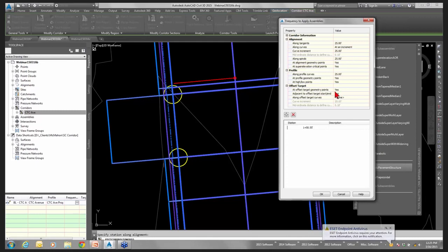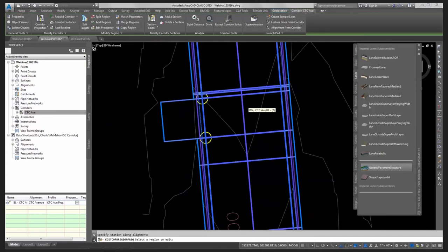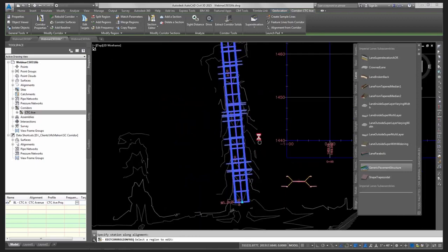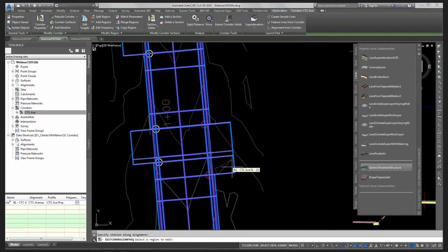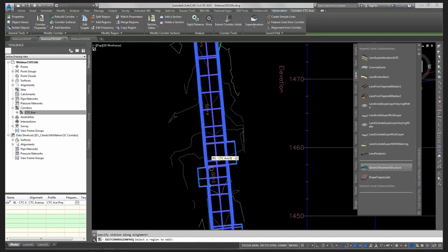So this is a new feature in 15, if you didn't know it. If you're running 14 or earlier, here's a nice feature. If you do a lot of corridor targeting, it would be worth upgrading to 15, because it's definitely a time saver. Right now, I have 7 driveways. I would have to pick 14 circles manually. It takes time. This kind of does it for me. So those are my driveways coming in, and you can see everything turned out really nice.